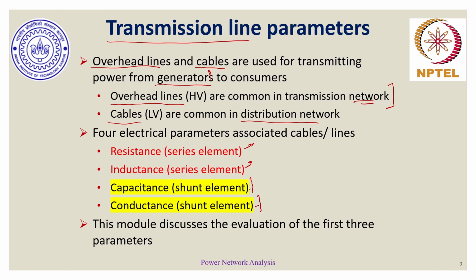These conducting bodies need not be parallel line conductors. For example, the presence of earth or nearby insulating material or nearby charged body like a tree or a tower or a house or a wall or a humid moist surface near the line conductor, that can also influence the line capacitance. In addition to its own property, capacitance also gets influenced by nearby charged bodies which need not be conductors in themselves.